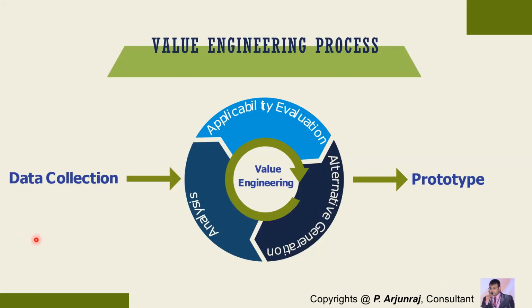The first one is data collection, which is nothing but the information base. Next, you are going to analyze the requirements. Analysis is nothing but a function analysis, which is the requirement analysis. So you are going to analyze what is the necessary basic function or secondary function. Then you are going to generate the ideas. I told you the function of a motor is to transmit torque, the basic function. You also have various secondary functions. So you have to generate ideas considering all the requirements. And then after generating ideas, you also need to evaluate the ideas with the help of the team members.